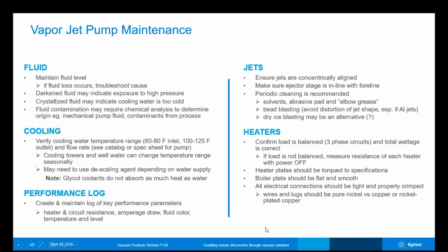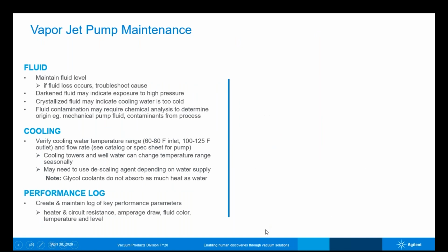Okay, so let's talk about maintenance for a second here. I'll try and keep the screen a little bit clean, being conscious of the time as well. When we're looking at maintenance, we're looking at the vacuum fluid or the pumping fluid. Sometimes I refer to it as pumping oil, although there are different species that can be used. We need to maintain the fluid level inside the pump. Obviously, the lower the fluid level, the more problems we're going to see with the pump. We can see overheating, and destruction of the fluid through overheating and, let's say, cracking of some of those hydrocarbon fluids.